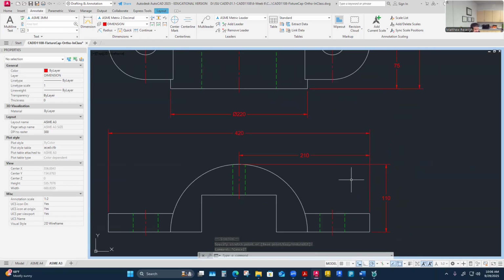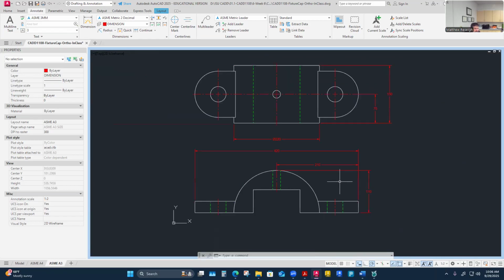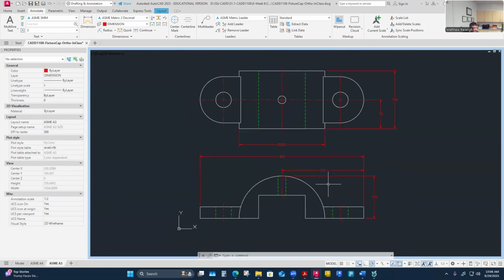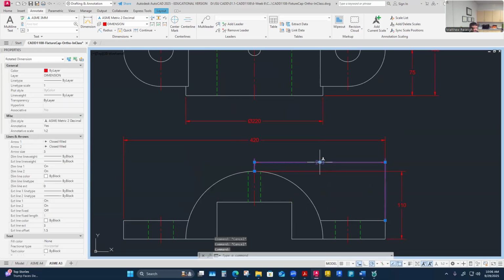So it's kind of located. We've got the size 220, or sorry, 150 by 220. Then the location is 75 up from the front face, and it's kind of coming in maybe from center. I'm actually thinking of this not necessarily as the datum being this point, because I don't love these big radius datums actually. I'm viewing this 210 as coming mostly from the center part over to the edge. That one might not be on my other print, but I do like that dimension. It kind of locates a bunch of different stuff actually.